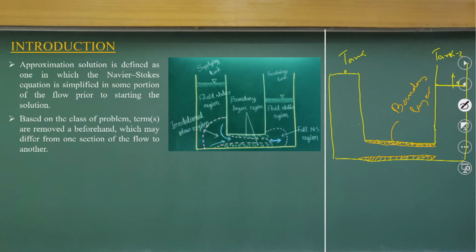So, there will be boundary layer formations because of the presence of these two walls. As the fluid particles are coming, not all the fluid particles here will be active in the flow going through this. The flow will come into the regions very close to the walls, and the flow will go like this, come, and go like this.